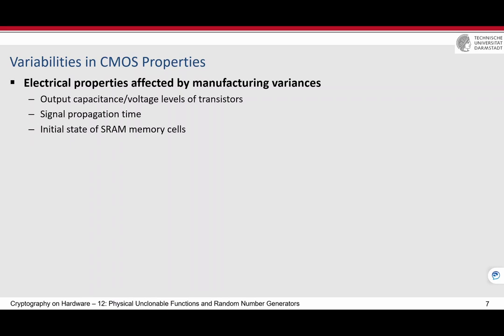You know, for example, the delay of every transistor, or the voltage level of every transistor. They are built completely in the same way, but there are super small differences, which is also referred to as process variation. It means that during the fabrication, there are some variations, and this makes every chip completely individual and different to any other chip which is produced at the same time with the same pattern, with the same masks and everything.